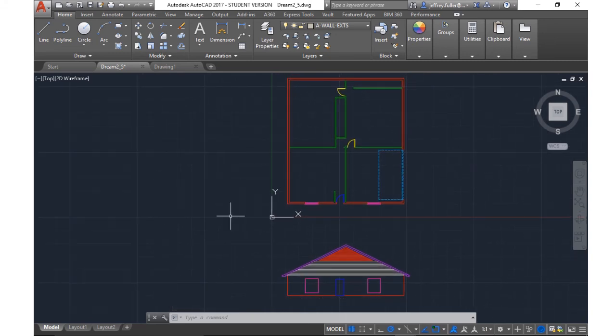Let's see, at the bottom of your drawing area, there is a command dialog here, command box or command bar. You can type stuff into this, or you actually don't have to type it into this. You can actually type it right on the screen. But this will show you any commands associated with whatever you're doing or about to do. So if I click on line, I go down here and it says line, specify first point.